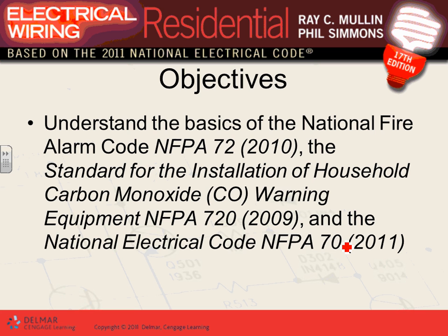When it comes to the fire alarm system, there is an NFPA document called NFPA 72. NFPA 72 is called the National Fire Alarm and Signaling Code. They changed the name. This document will tell you where you need smoke detectors and heat detectors in any building. Can I get you guys to understand: if you want to know where you need to put a smoke detector in the building, would you find it in the National Electrical Code? No. Where would you find it?